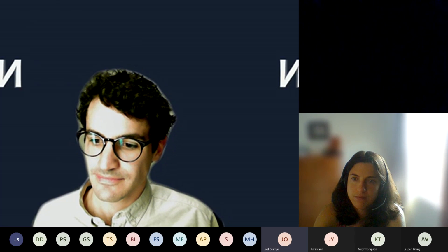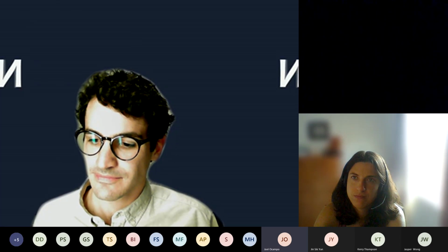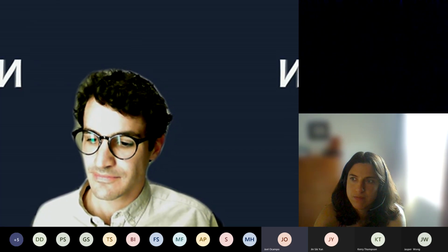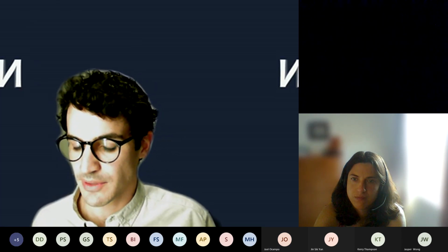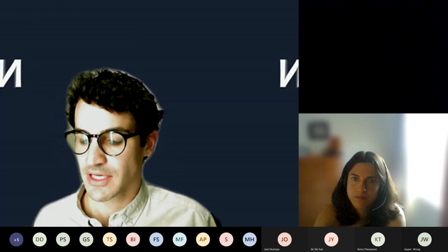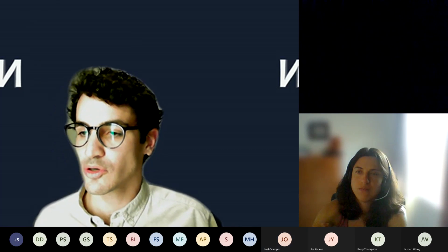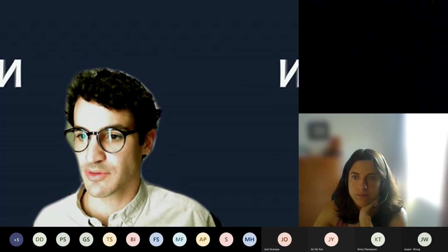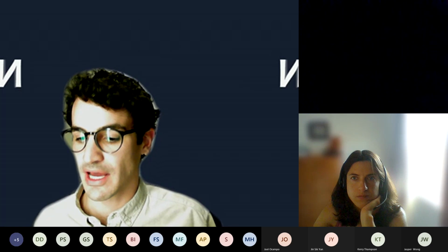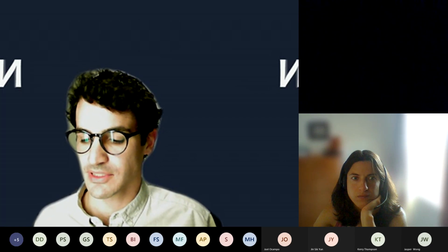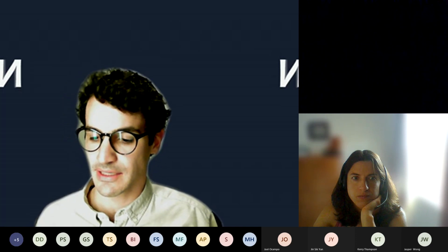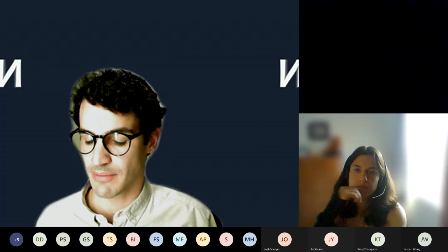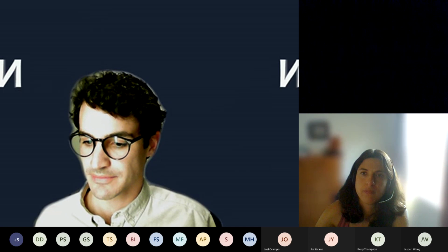So it's like a delete and replace, or is it going to update the model? No, it's actually going to create a new instance of that geometry. So if you close your model and then run the Dynamo script again, you're going to have two instances of the geometry. So it will probably be better if you delete it and work with the parameters if you want to make some changes.